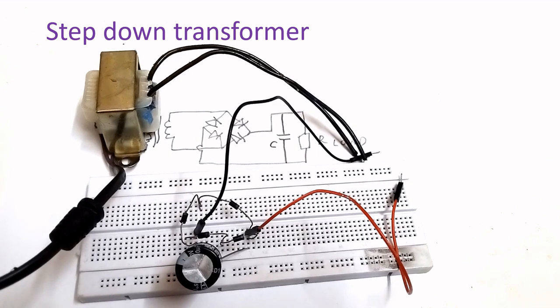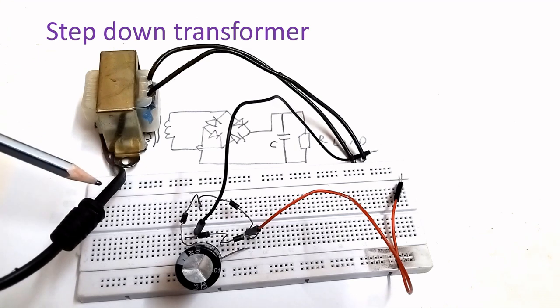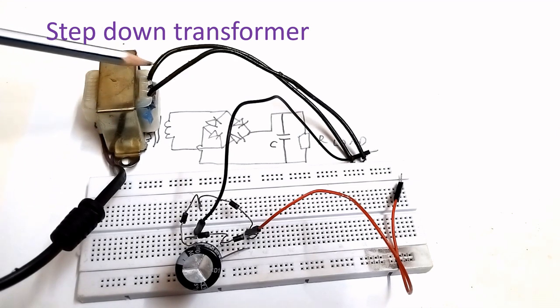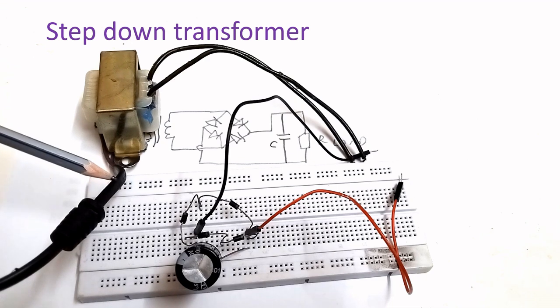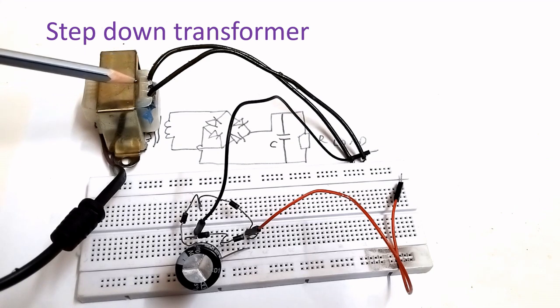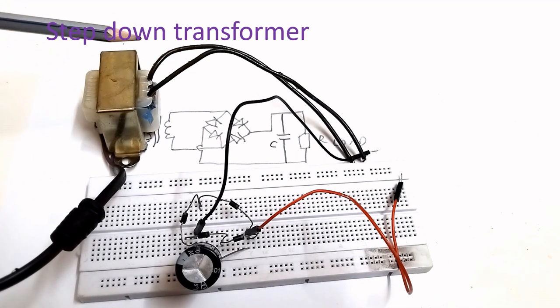This is a transformer which I can use for the power supply. This is a secondary output. You can see 2 wires going, that will be 12 volts, and this is the primary connection to the mains supply. The turns ratio will decide the voltage in the output. Suppose this is 230 volt and this is 12 volt output. That's a step down transformer, and you need a turns ratio of 230 to 12 to get a step down transformer.